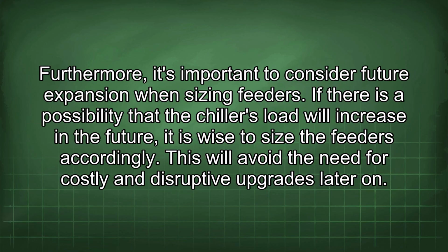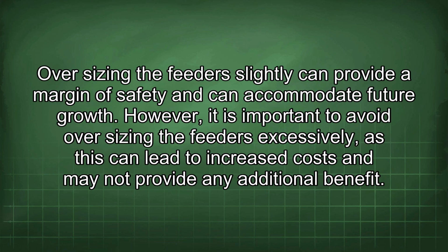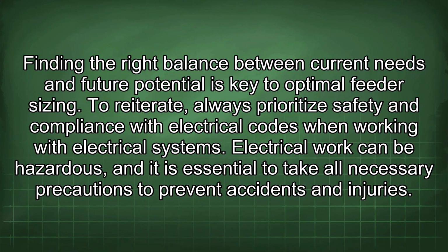Furthermore, it's important to consider future expansion when sizing feeders. If there is a possibility that the chiller's load will increase in the future, it is wise to size the feeders accordingly. This will avoid the need for costly and disruptive upgrades later on. Oversizing the feeders slightly can provide a margin of safety and can accommodate future growth. However, it is important to avoid oversizing the feeders excessively, as this can lead to increased costs and may not provide any additional benefit. Finding the right balance between current needs and future potential is key to optimal feeder sizing.